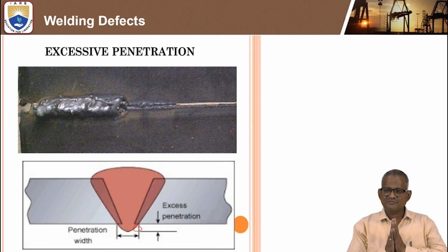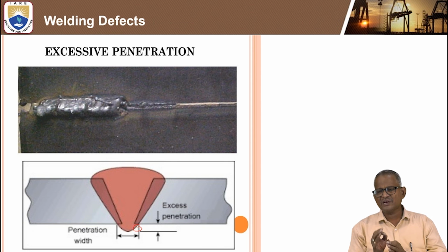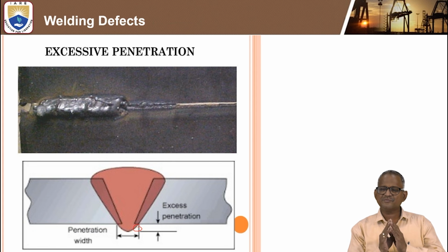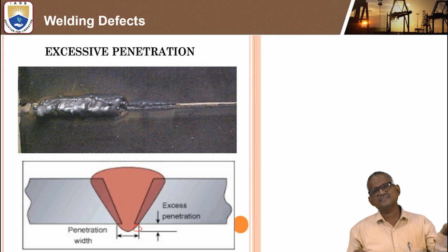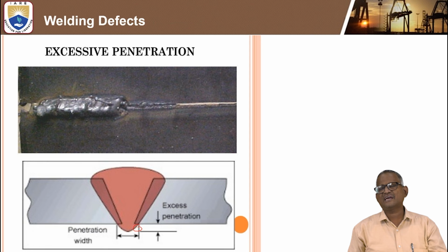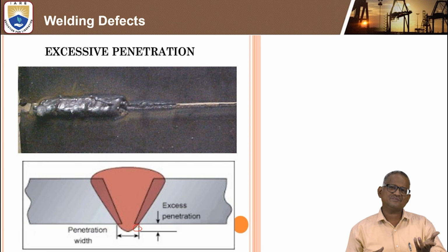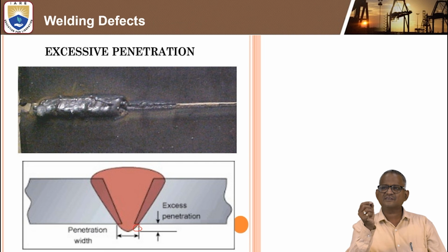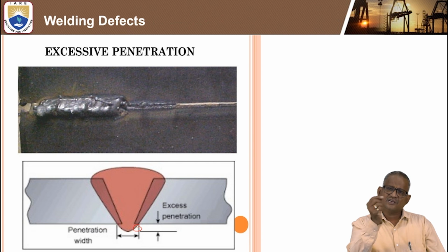Mainly in any manufacturing process, either casting or forging or welding, there will be some flaws. All processes will be flawed, and defects will be there. Even casting has casting defects like blowholes, sand drop, shrinkage. Forging also has forge cracks, inclusions, so many defects may occur.